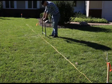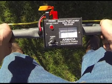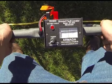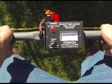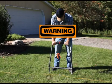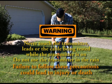Continue to zero in on the fault by following the initial needle kicks. When you are directly over the fault, the needle will cease to kick. Mark this spot for repair. Before repair, turn off the transmitter and disconnect it from the cable. Never touch the transmitter, leads, or the cable being tested while the transmitter is on, and do not use the transmitter in the rain. Failure to follow these precautions could lead to injury or death.